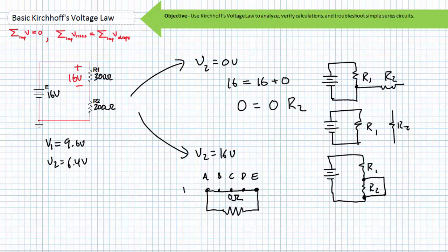In effect, this conductive clip connecting columns A through E, or F through J, inside individual rows on a protoboard, acts like a low resistance path placed in parallel to the resistor in question. Anything placed in parallel with such a low resistance path presents no opposition to current flow and effectively removes this resistor from consideration.